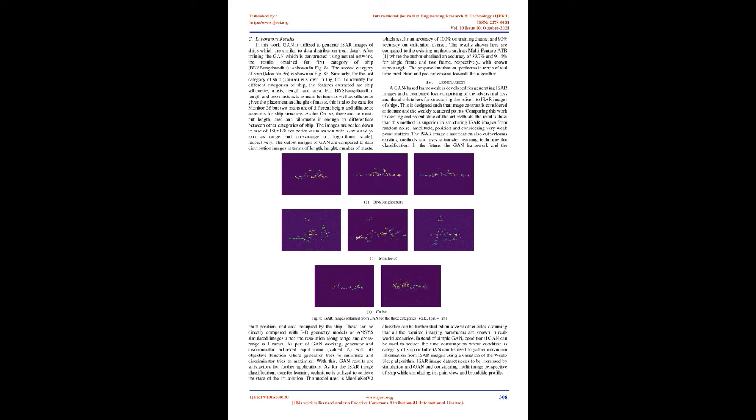Open the RADAR pre window, enter the radar requirements as shown in Table 2, and generate the radar setup. Set the ray density per wavelength as 0.1 and check edge correction in the setup window. The model and setup are simulated using RADAR post. Simulated results are imported and ISAR images are obtained as shown in Fig 7.